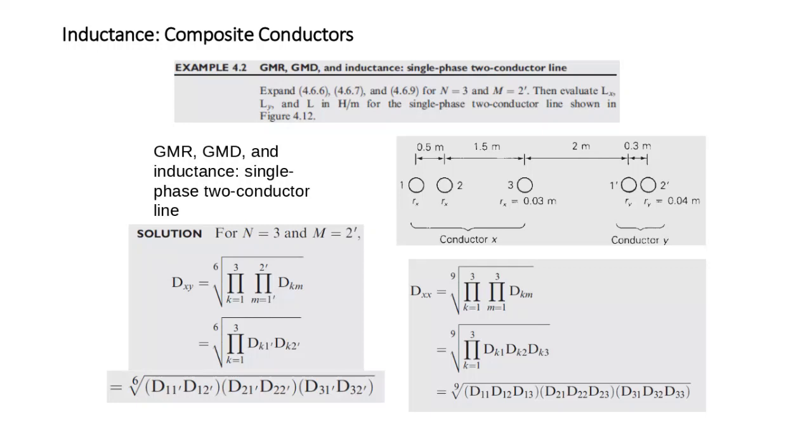If they go higher, they need a 3-phase system, connected just from the DP. Instead of single phase, they can connect the 3-phase red, yellow, blue from your DP. That is not a problem. They have a swimming pool, for example, and want to heat it. They need 3 phase because of the heater. So even in houses, you need single phase or 3 phase.